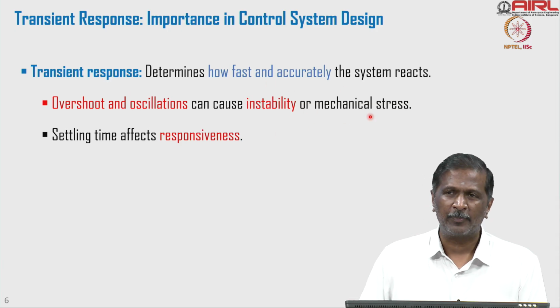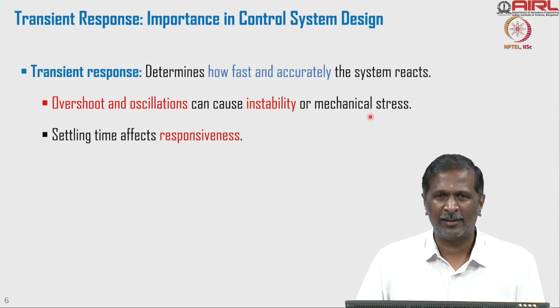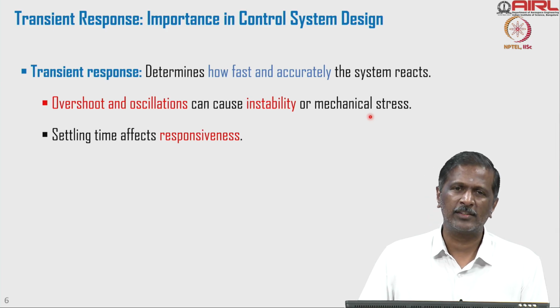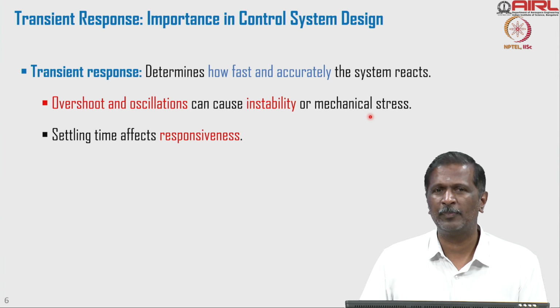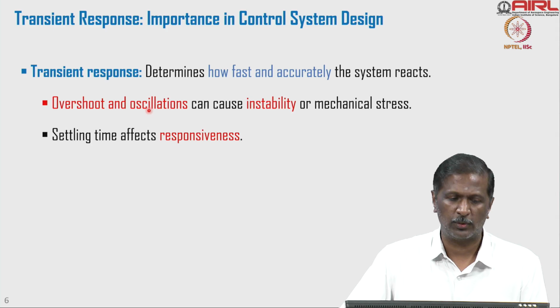Think about it, your speed going up and down and it takes time to settle, which means your motor will keep changing the voltage and input. That will also cause some vibrations in the whole structure, that will also cause fatigue, fatigue cracks and all that, or some joints can get loose. So it's very important to understand how much oscillation is going to be, how much is the overshoot. How fast it settles is also very important.